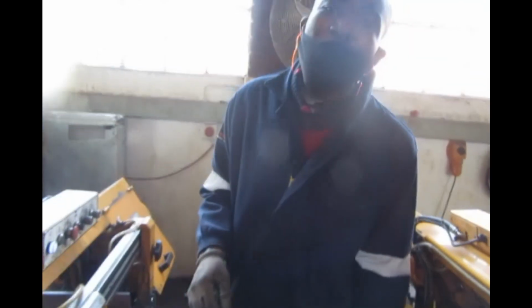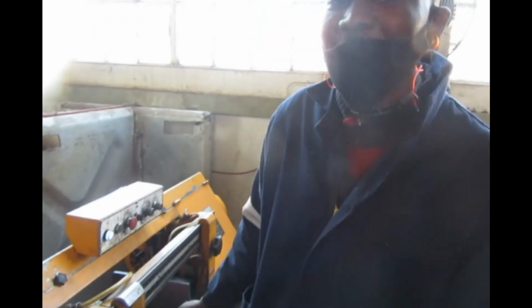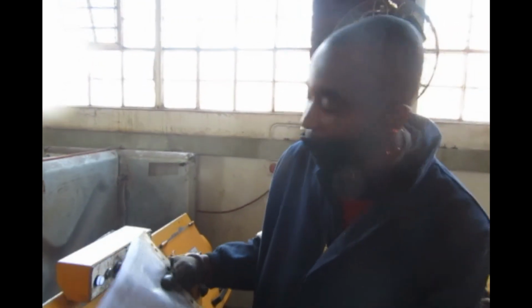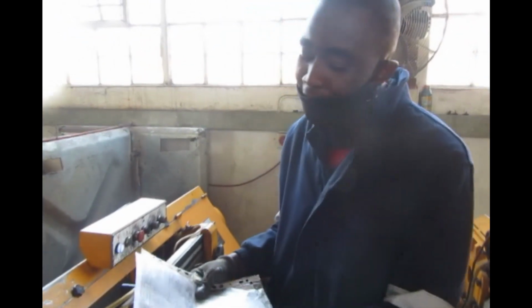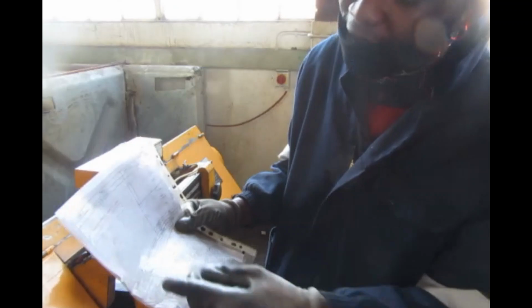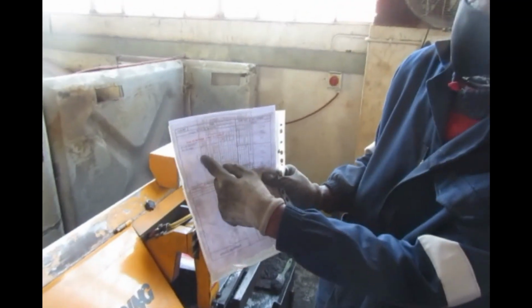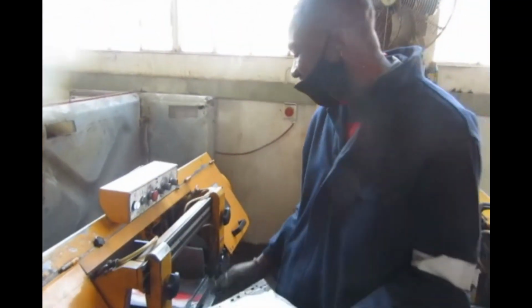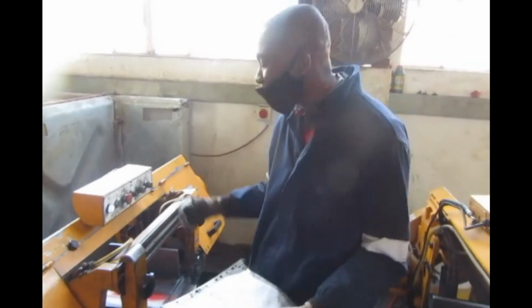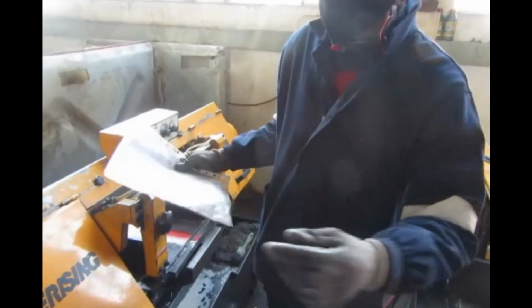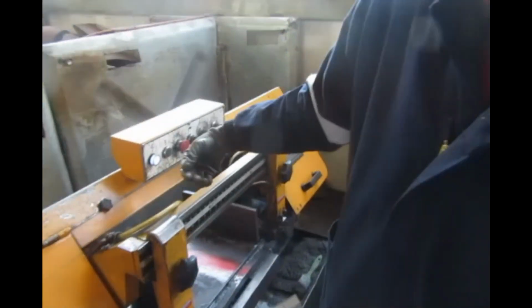So what are you doing here? Right now I'm cutting a scrap. Firstly, you have to remove the scrap from the test piece that you are given, according to the job sheet and the instructions that you are given. After I cut my scrap, I'm going to cut. I have a tensile and 2 bends that are needed according to the description. So first, I have to remove my scrap from both sides, so I have to cut both sides of this test piece.